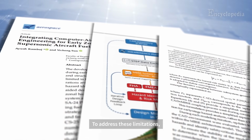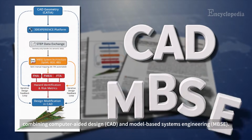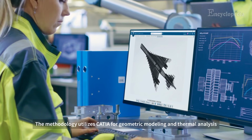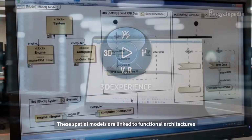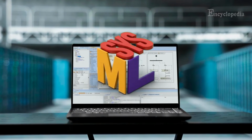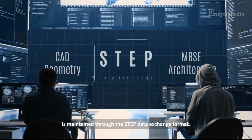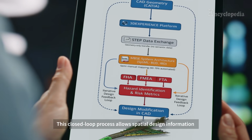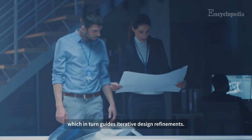To address these limitations, this study proposes an integrated framework combining computer-aided design and model-based systems engineering. The methodology utilizes CAD for geometric modeling and thermal analysis within the 3D Experience platform. These spatial models are linked to functional architectures developed in Cameo Systems Modeler using SysML. Interoperability between the CAD geometry and the MBSE architecture is maintained through the STEP data exchange format. This closed-loop process allows spatial design information to inform the functional safety analysis, which in turn guides iterative design refinements.